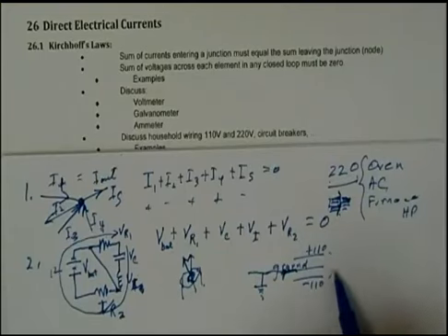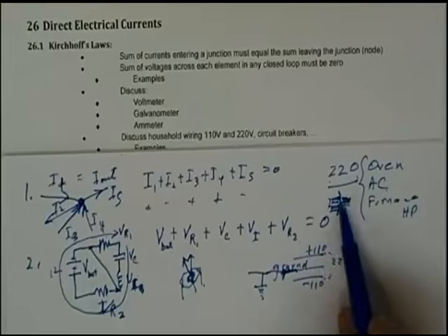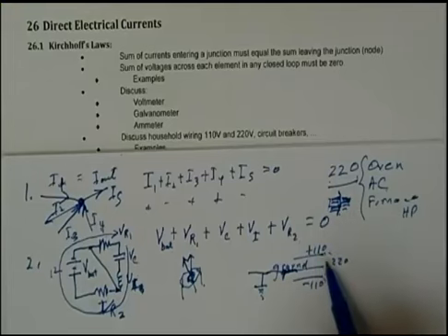So between these two outer ones, there's 220 volts that we can use by going from the outer one here to this one. Or if we just want 110, we pair the breakers in the house, or the different circuits, as I should say, either from this side or from this side about equally.